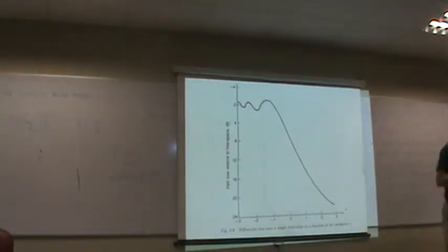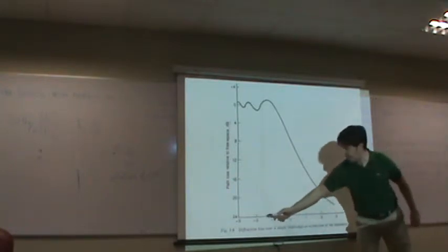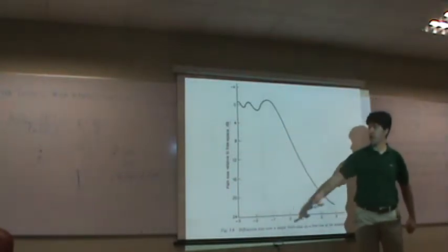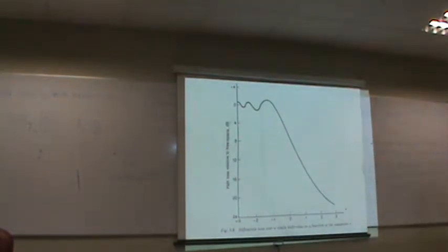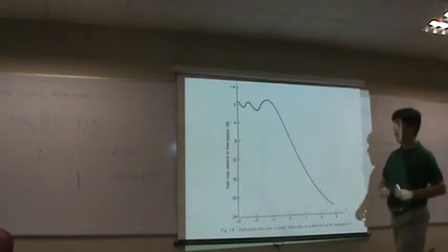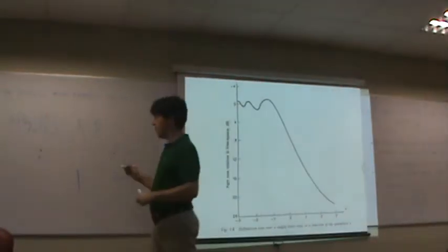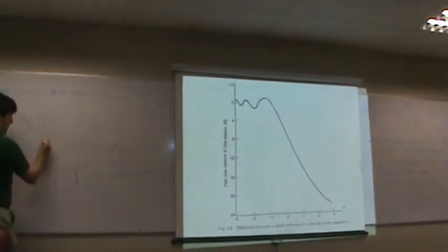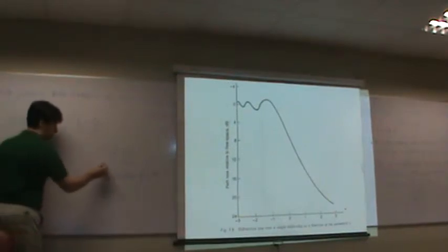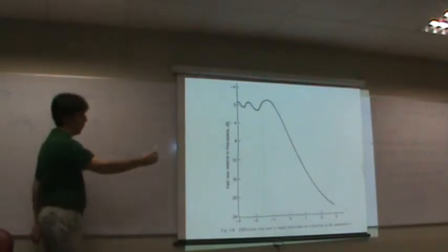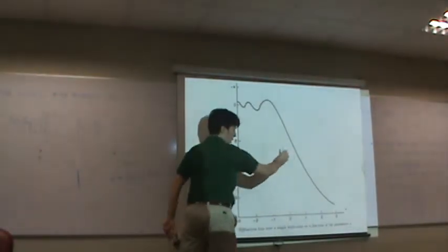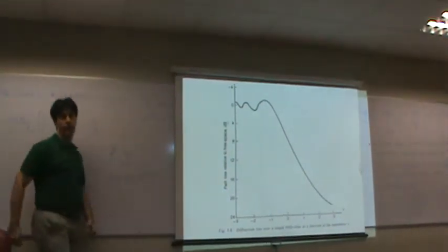Why do we have to lower the obstacle? Negative values of V mean negative H, which means a lower obstacle. Because we have to free the first Fresnel ellipsoid. Any object entering the first Fresnel ellipsoid will cause a strong reduction in the received field.